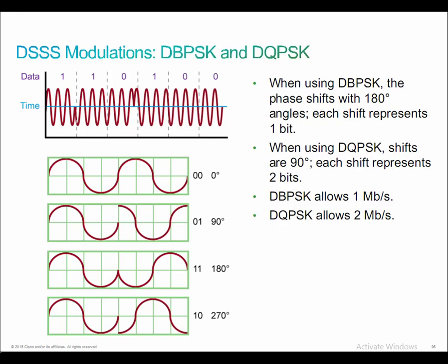If the next microsecond is unreadable because of interference or whatever it might be, 10 other signals are still going to be available in parallel to confirm or deny, I guess, the nature of that particular bit or that particular symbol. All right. So if you do the math, we're sending one symbol, a bit, I guess, for lack of a better term, each microsecond. That means we're sending 1 million symbols per second, which then converts to 1 megabit per second.